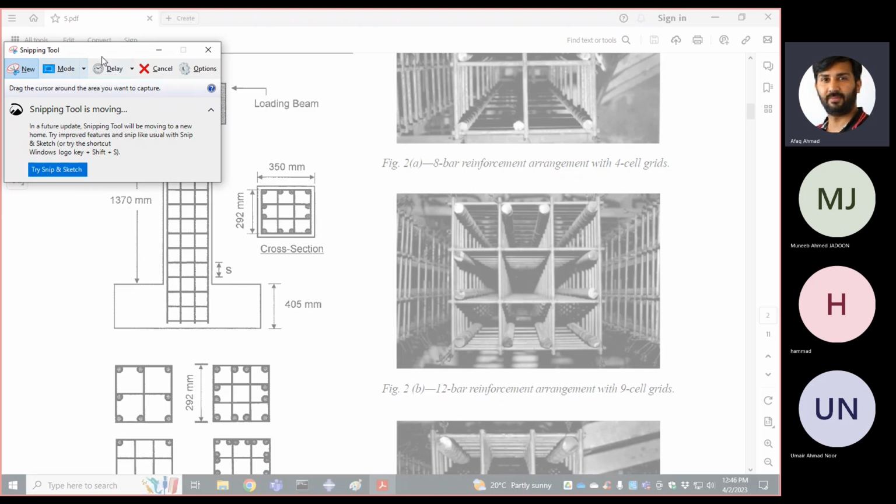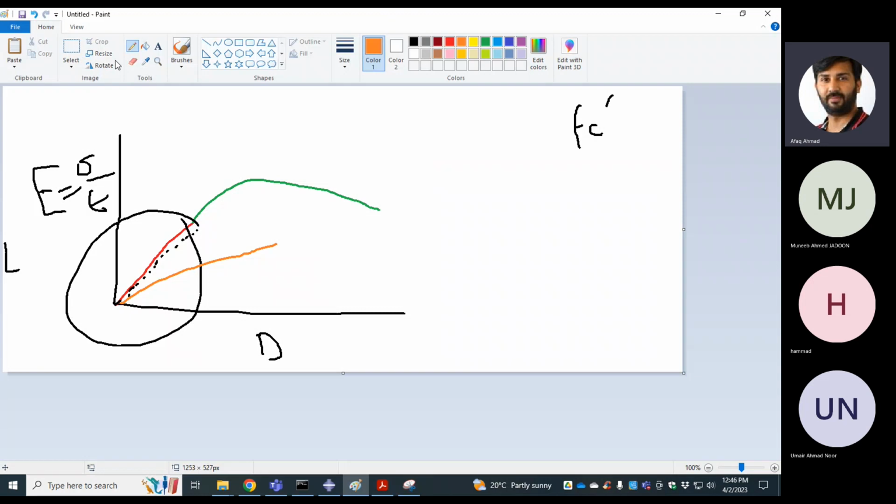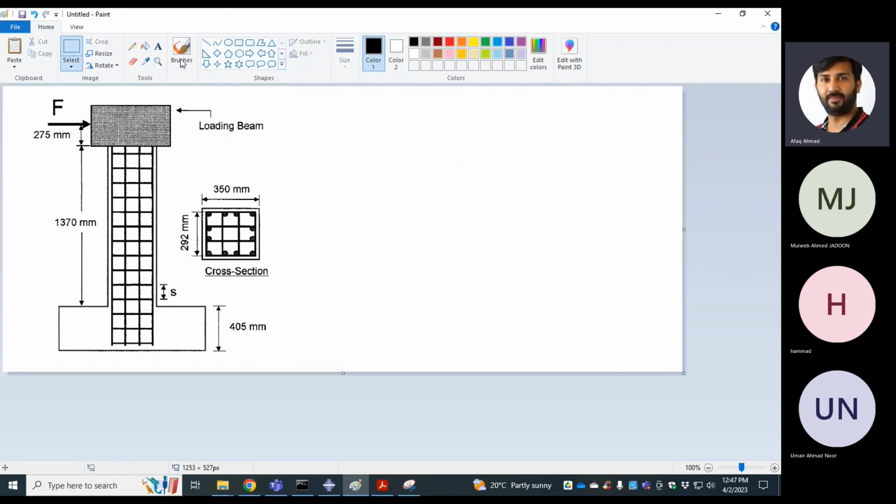So you should be very smart. You don't need to draw the whole geometry. For example, in my case, I only model from this point to this point, and then I model the column in two parts. Part one is the concrete column, and the steel plate or the hard concrete will be part two. And I don't need to model the bottom one.